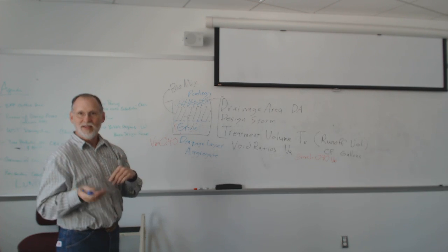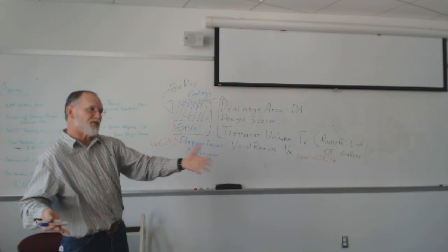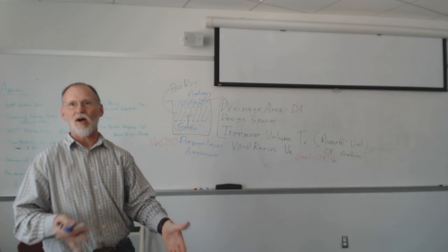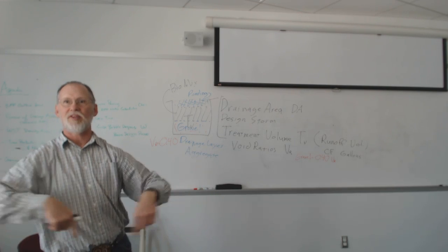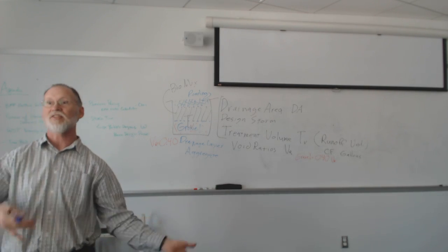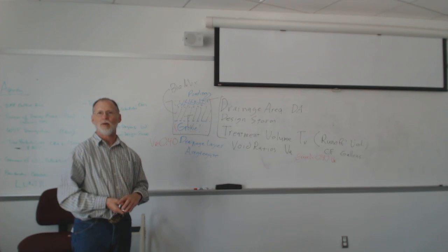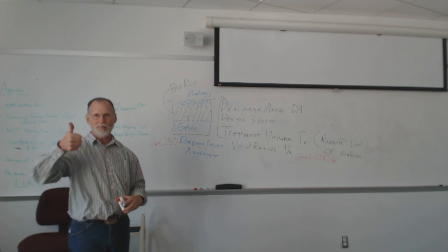and it's not that hard to prove because you know how much gravel weighs for solid gravel. So you can fill a container with it, weigh it, and say, oh, if it was solid limestone, 1 cubic foot rock, it would weigh this much. It doesn't, it weighs less. The difference is the void ratio. So it's pretty easy to measure, so I'm assuming it must be pretty darn close. I'm taking it on faith.